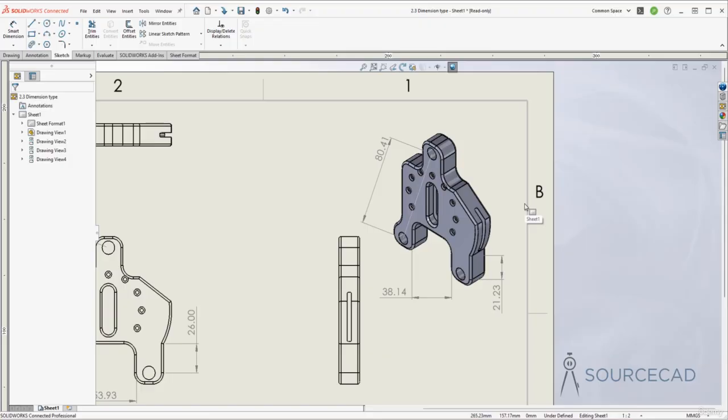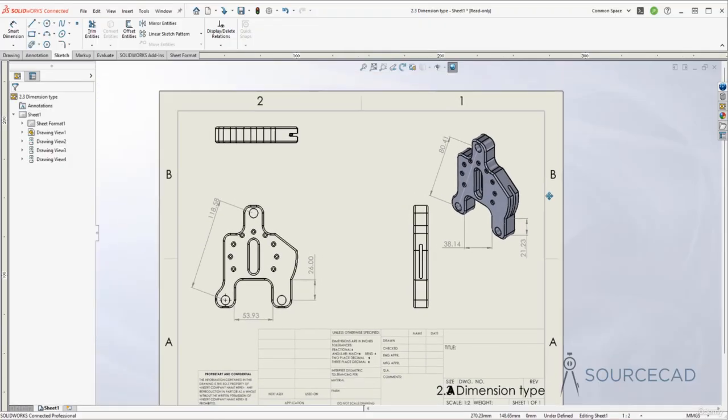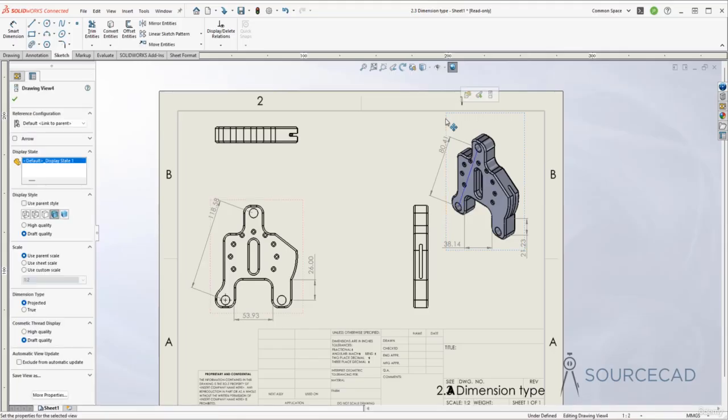So what's the solution? Whenever your drawing and your drawing sheet are both not parallel, in that case you can use the true dimension type instead of projected. Now let me show you what that is. But before that, I'll simply select this view. And when you do that, the drawing view property palette will show up. Here you'll see the dimension type. So dimension type is selected as projected, and we have the projected one for this case as well.